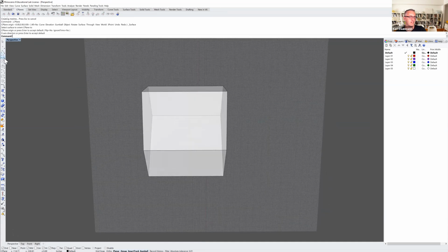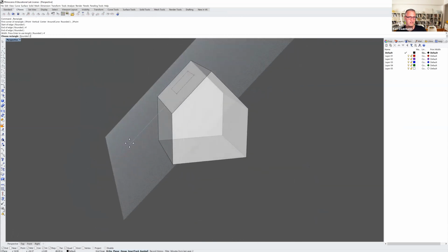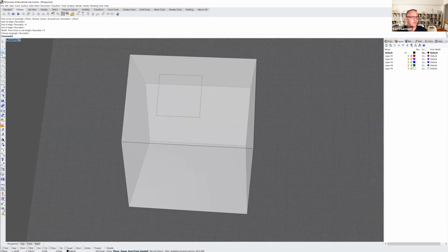So when I draw something here and I want to draw something that's 4 feet by 4 feet, I'm drawing very specifically on that surface. And maybe I want to be very specific about exactly where it is on there, that it's maybe over 2 feet and down 3 feet. And now I can set this corner to there, and delete this line.